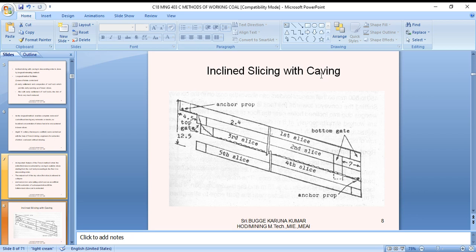In an experiment in Karanpura coalfield for making the artificial roof, 50 to 60 steels were laid on the floor to form a mesh of 40 centimeter by 40 centimeter, over 1.5 meter wide, with 25 mm rods. 2 mm galvanized wire netting with a mesh of 20 mm was laid, adjoining rolls overlapping by 25 centimeter. These were tied to the steel strips mentioned above every 50 to 60 centimeters.